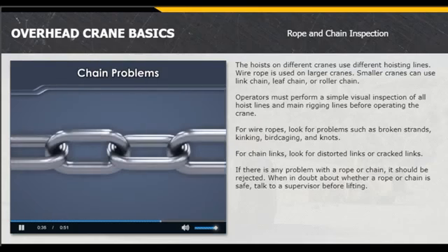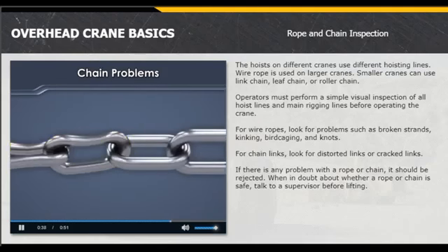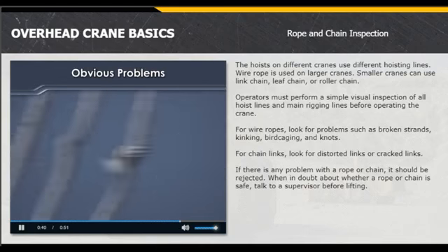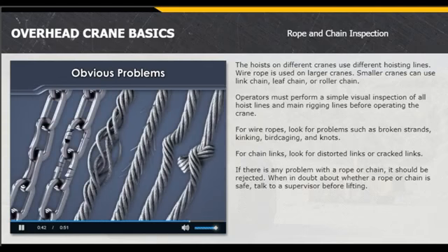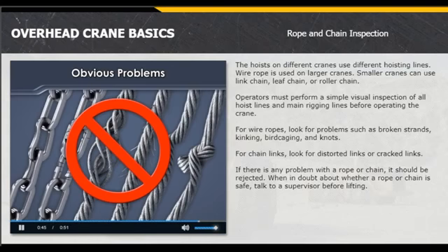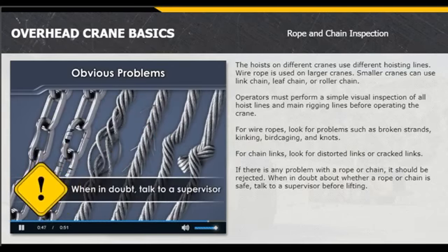For chain links, look for distorted links or cracked links. If there is any problem with a rope or chain, it should be rejected. When in doubt about whether a rope or chain is safe, talk to a supervisor before lifting.